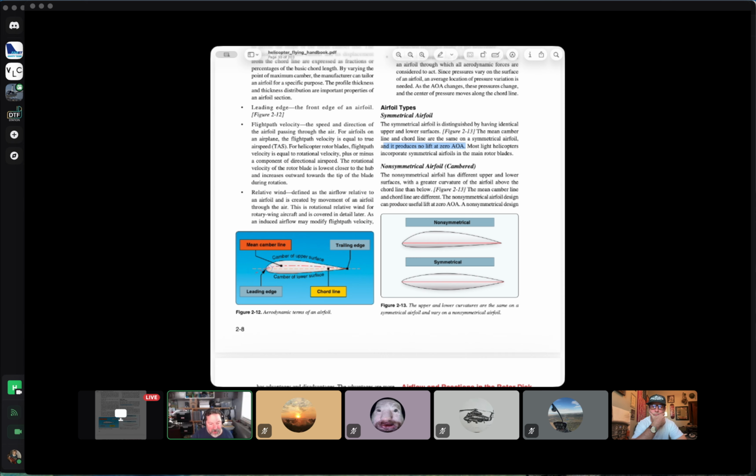So those of you that have flown an R44 know that when you turn the hydraulics off for the hydraulic test, you do an X pattern to make sure there's no binding or restrictions that have been hidden by the hydraulics, and then you turn the hydraulics back on. You never test the collective.